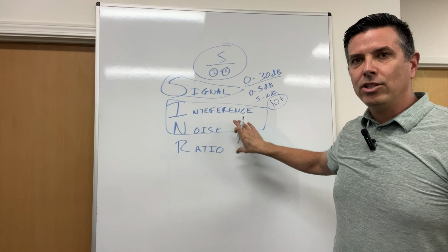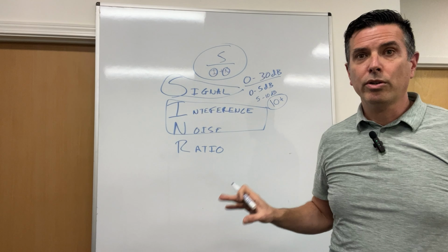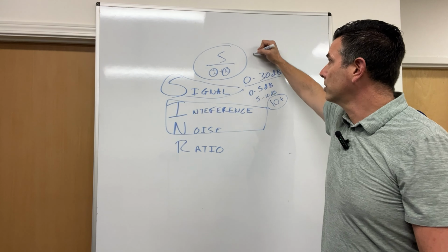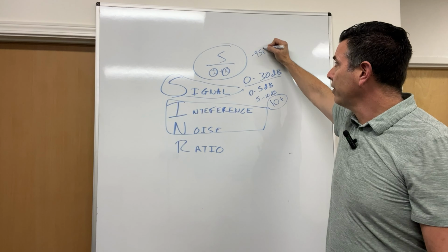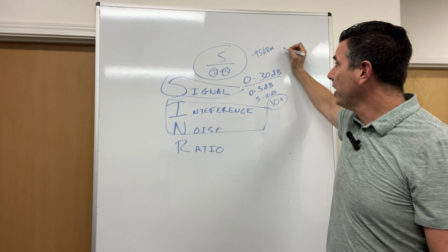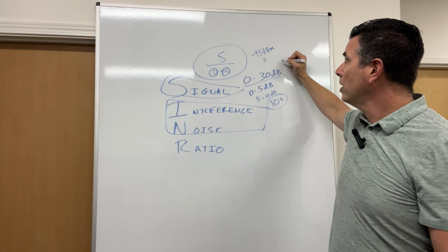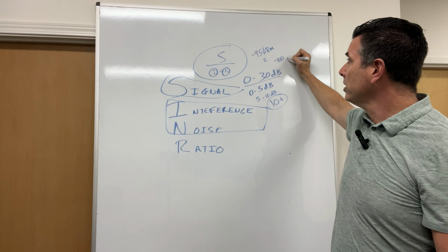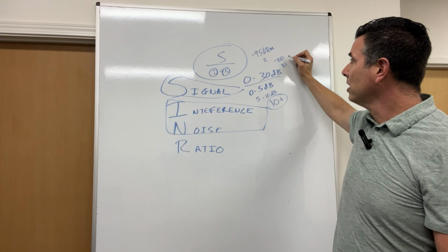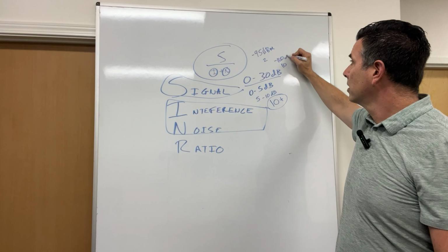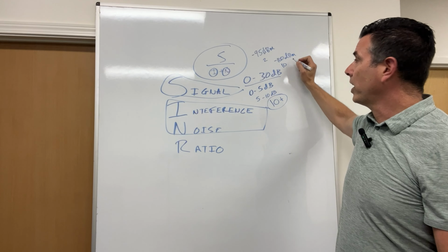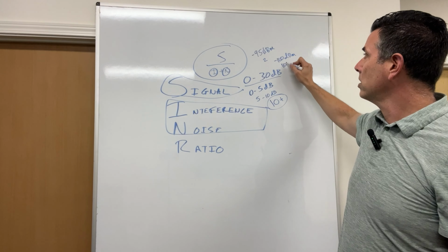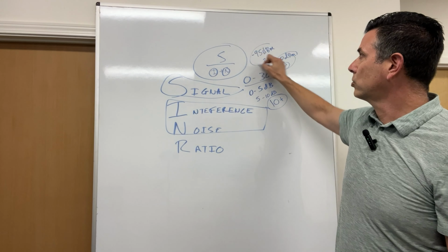Now, when you are signal hunting, when you are looking for a donor site, if you have two options, one that's neg 95 dBm RSRP, but the SINR is 2. If you have a neg 100, but the SINR is 10, go with the 10. So if you're doing an off-air system, it's more important to have a clean channel than a strong channel.